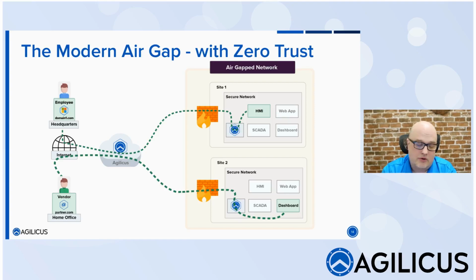There's a lot of diagnostics that some devices produce, and you need to be able to get to the vendor. And it's a big directory full of log files where you need to go plug USB keys in. That's how they got Iran to Stuxnet. You don't want USB keys walking into your plant. And then you want an audit trail. You want to know who did what when.